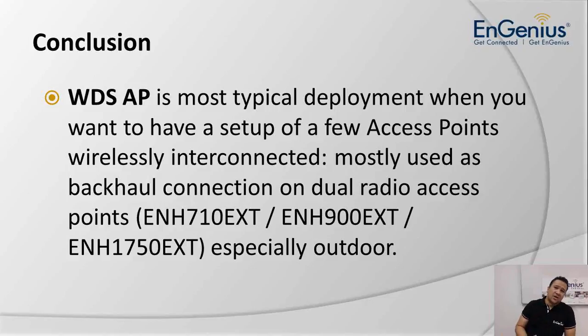For indoor, normally the wiring is not so complicated. It's recommended to use a direct wired connection to PoE switches if you're doing an indoor deployment.